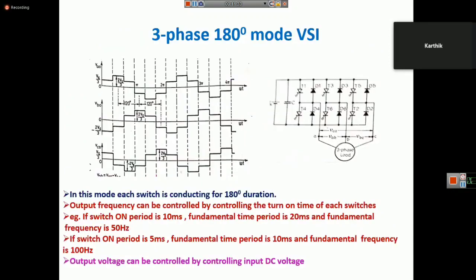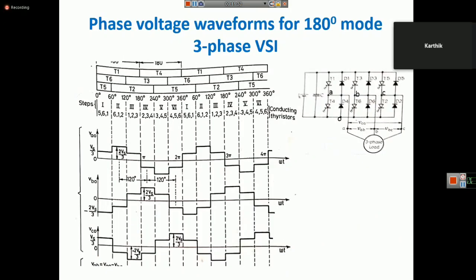2 VS/3. Okay, that is 2 VS/3. And actually this requires a detailed section. Even then I will just inform, because in the power electronics class we find this voltage with the equivalent circuit. Actually these voltages VA, VB, VC are given as input to the stator of the induction motor.